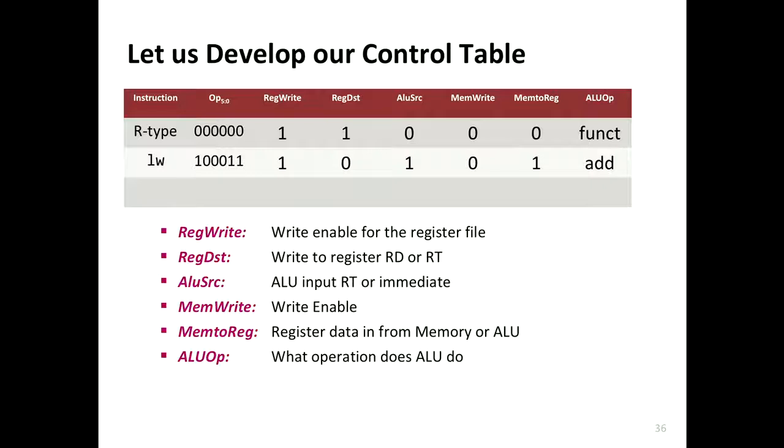Consider an I-type instruction like load word. It's an I-type, so you have a specific opcode for the load word. And you're loading. So are you going to write into the register file? Yes or no? Load word.